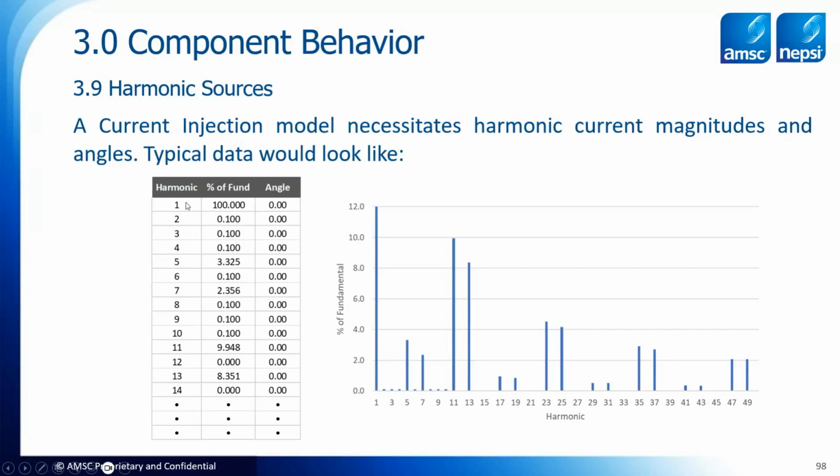Arc furnaces are a really interesting load that you may have to simulate, and if you do, you have to make sure that you also include non-integer components. These examples are good for ASDs, rectification devices, switching equipment, and even some source inverters will produce harmonics at non-integer frequencies.